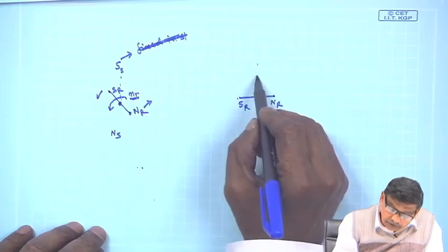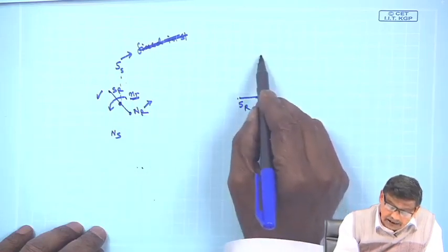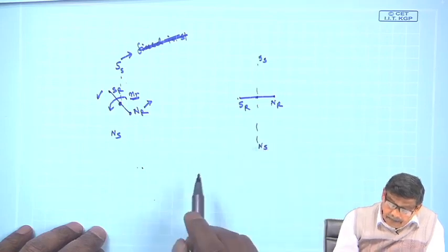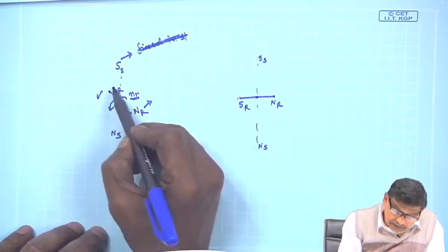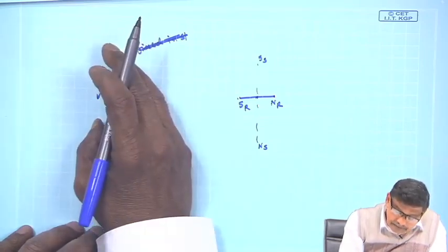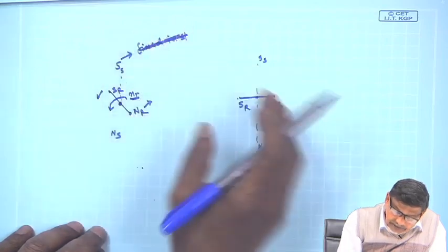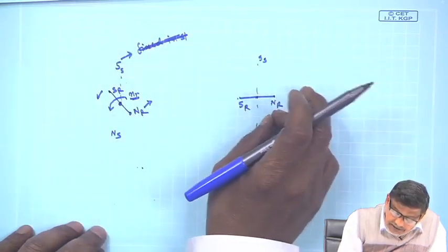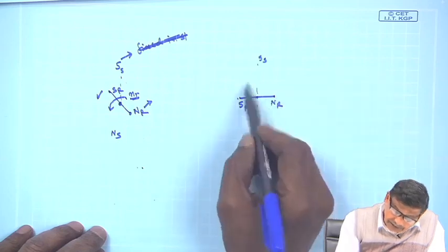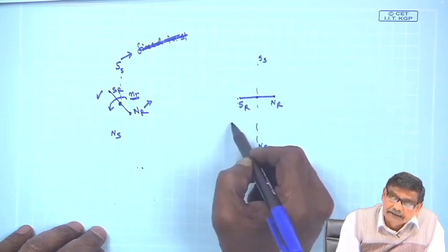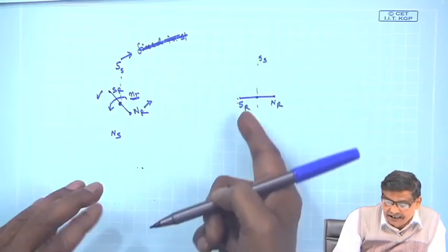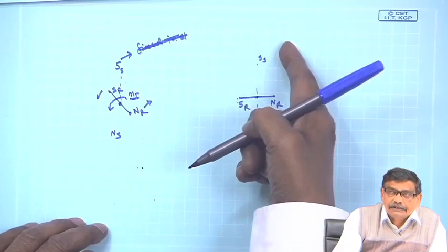and the stator poles, it was earlier here SS NS, and if I demand whatever torque it was producing at this instant of time, some time elapses, the rotor poles come here SR NR, then obviously once again the same torque exists here, but the magnitude of the torque depends upon how far this SR is from SS.